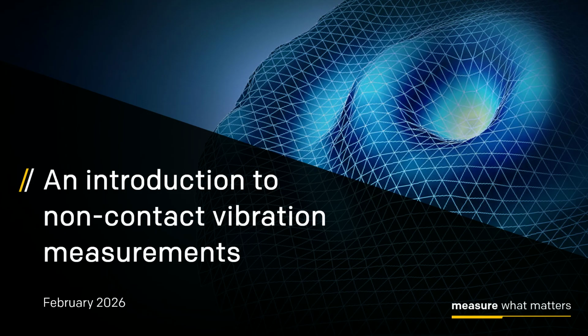If you are after displacement, then I would just start with displacement. If you have tonal excitation, then you can obviously go from velocity to displacement without any error. But if you have broadband, you might as well start with displacement. So the answer is none, because you are going pure displacement anyway.